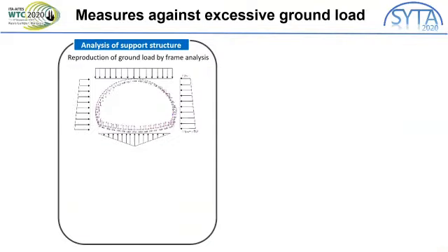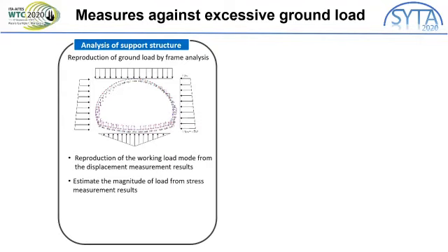Next, the support structure was redesigned based on the results of the main tunnel and pilot tunnel excavation. A frame analysis was adapted to examine the support structure. The working load mode is reproduced from the displacement measurement results, and the magnitude of the ground load was estimated from the stress measurement results of shotcrete and steel support. Then, the support structure was selected, which is acceptable for the reproduced ground load.